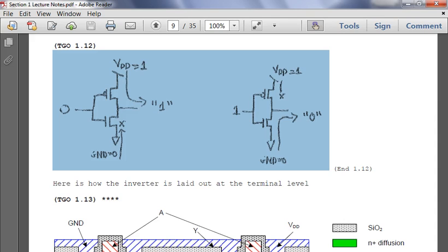Now, for the pMOS transistor, this is our pull-up portion. You have your source and your drain, and they drain to the same place, right? And so, for that, you have to create an N well, right? Specifically for the p-type transistor. And this would be tied to supply voltage, and this would be tied to ground. And we're going to be learning about metals in this, how you can tie metals to pins. These are pins here. You can actually fabricate that in order to create a circuit.